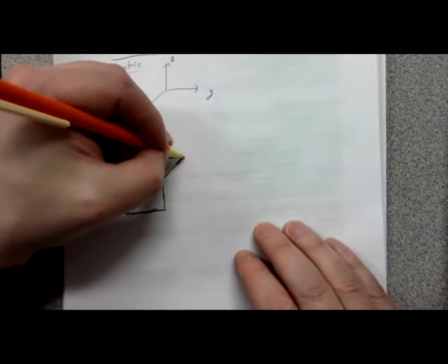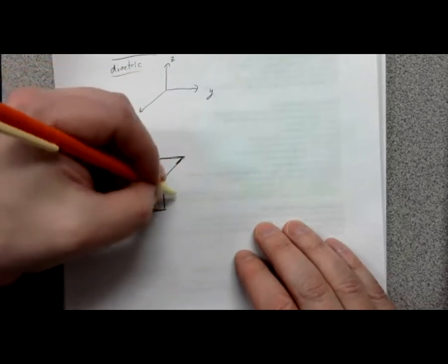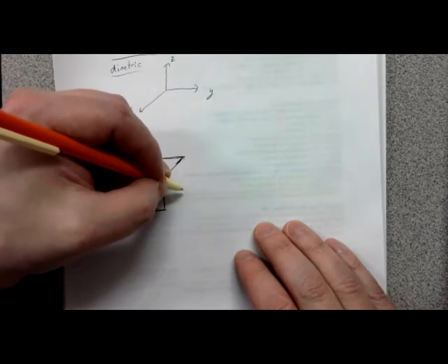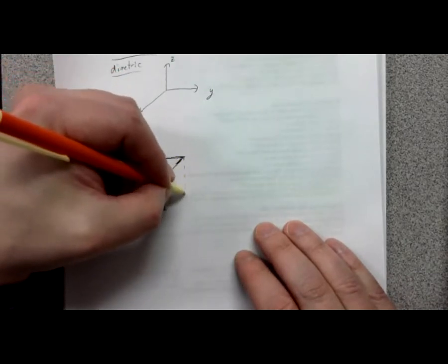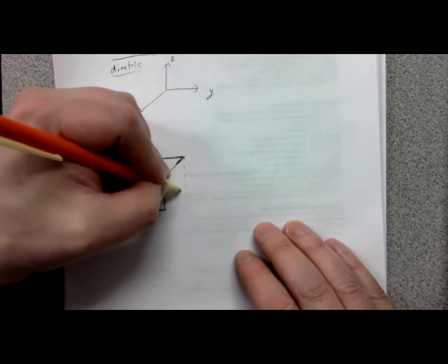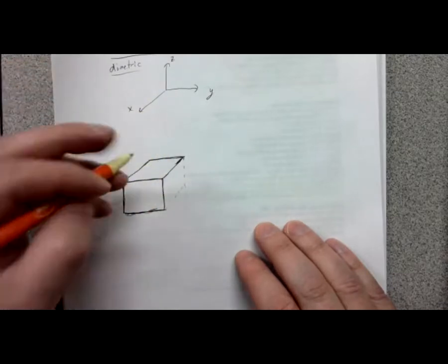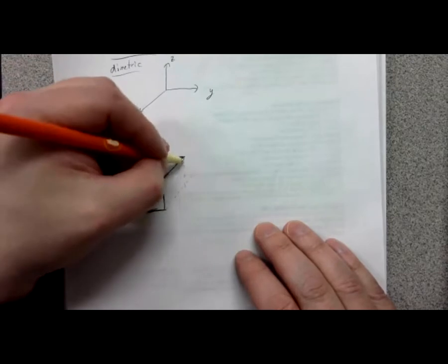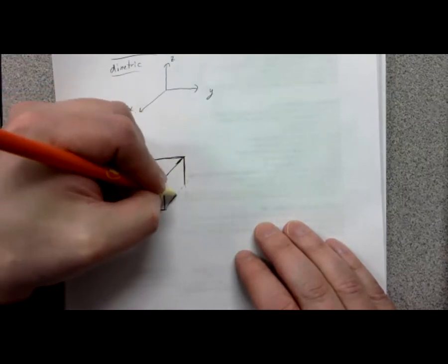A common mistake is, if I don't know where this corner is right here, we draw a line down, and you draw this line to meet it. No, don't do that. Dot this line down, and then dot this line up parallel in the x, what we define as the x direction, roughly parallel to these, and then find where the two intersect. And then go back and darken to the intersection